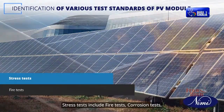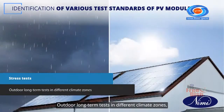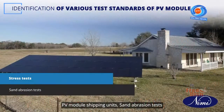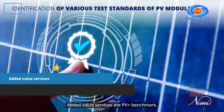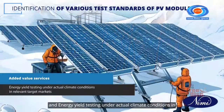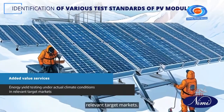Stress tests include fire tests, corrosion tests, outdoor long-term tests in different climate zones, transport and environmental simulation on PV module shipping units, sand abrasion tests, and snow load testing. Added value services are PV plus benchmark, qualification plus certification, and energy yield testing under actual climate conditions in relevant target markets.